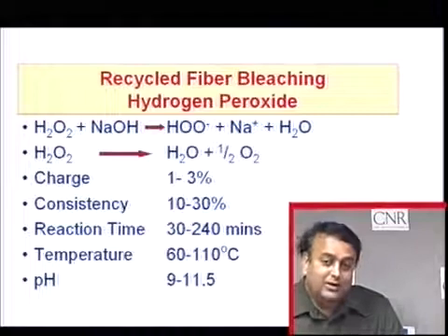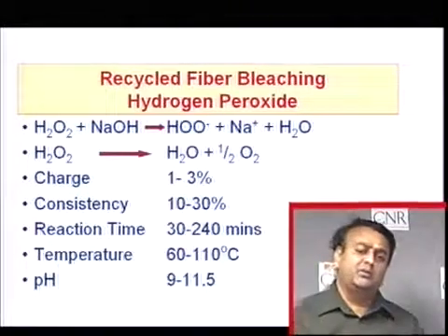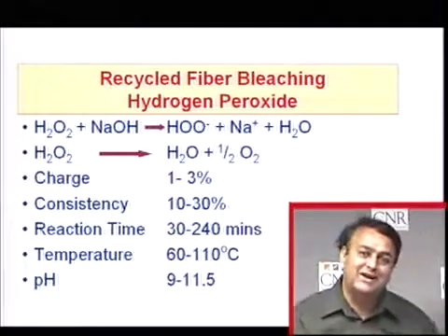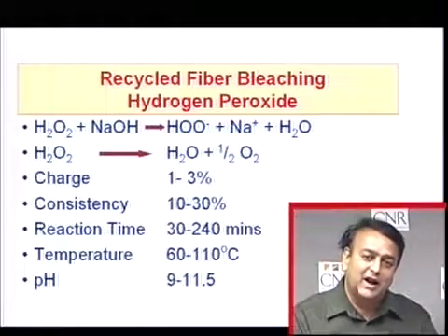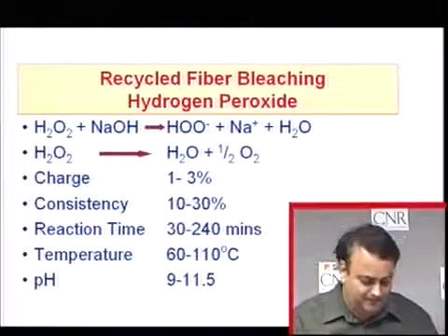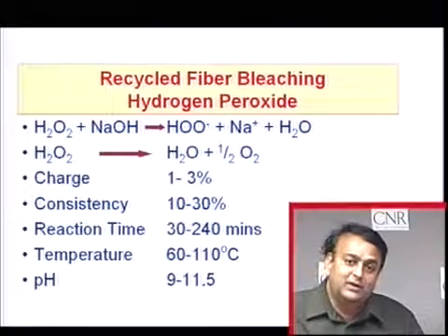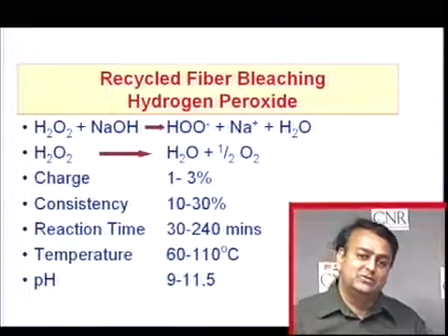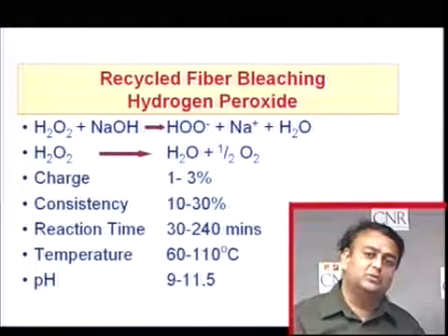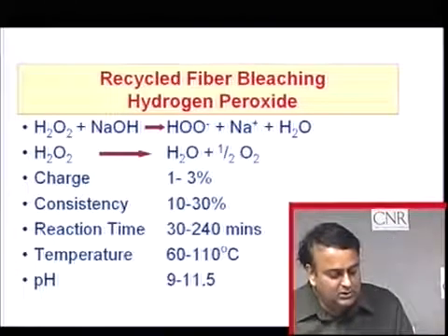Consistency: for peroxide, the higher the consistency, the better it is, because the concentration of peroxide will be higher at higher consistency, and the perhydroxyl ion can reach the fiber at a higher concentration, attack the fiber and make it brighter. Reaction time is anywhere from 30 to 240 minutes. Temperature and reaction time go together. With higher temperature you need lower time, or with lower temperature you need a longer time.